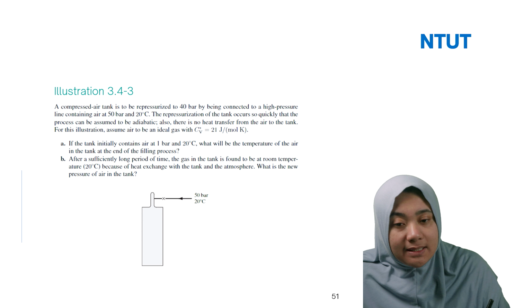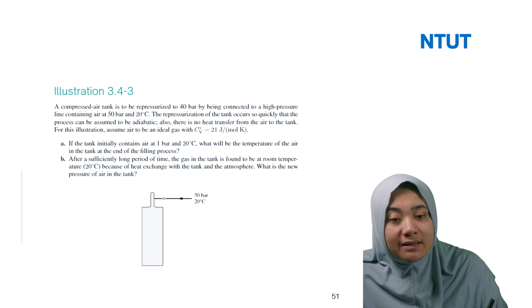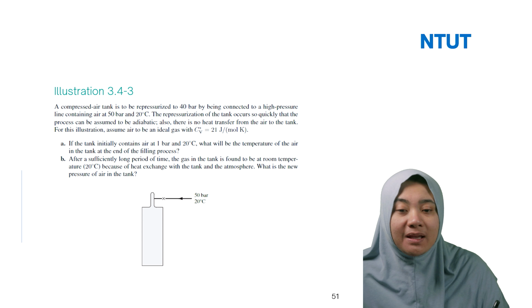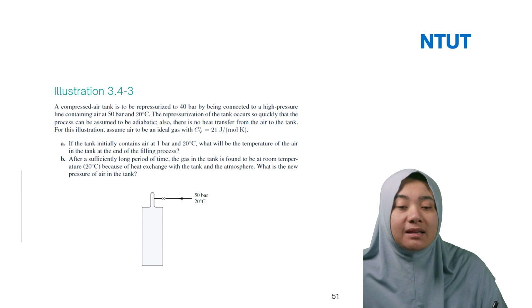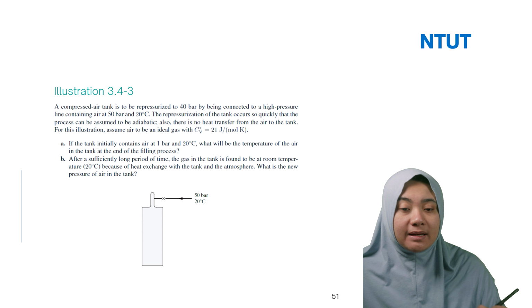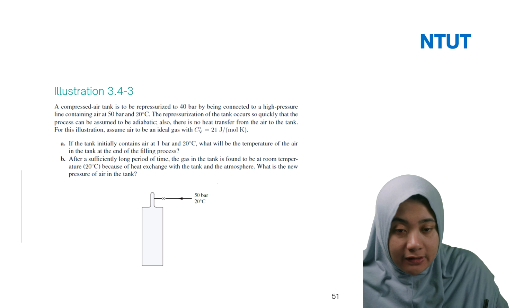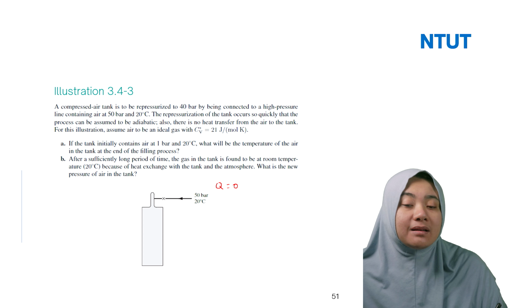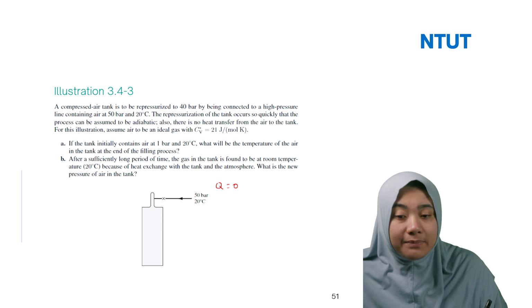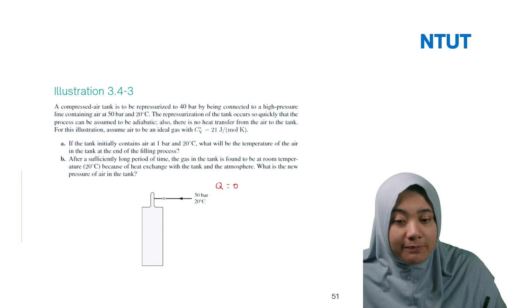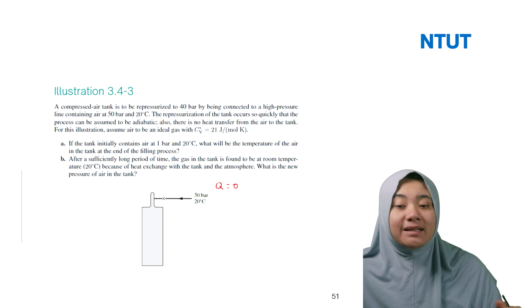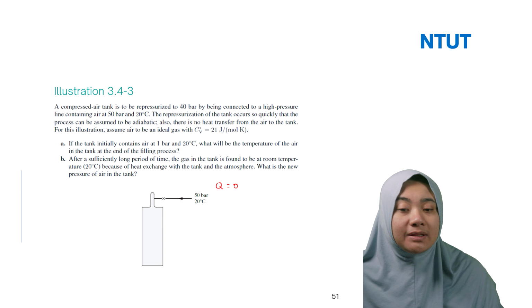You connect to the cylinder, and the repressurization of the tank occurs so quickly that the process can be assumed to be adiabatic. So there is no heat transfer from the air into the tank. And assume that CV asterisk is equal to 21 joule per mole K. So then we don't have Q, so Q is equal to 0. If the tank initially contains air at 1 bar and 20 degrees C, what will be the temperature of the air in the tank at the end of the filling process? So T2 is how much?